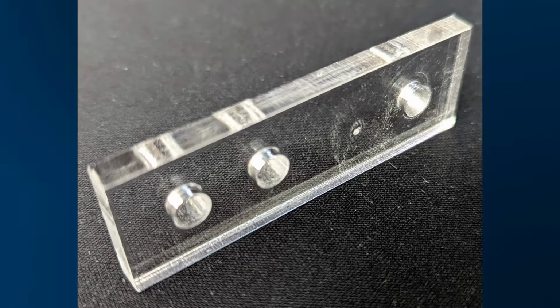Now, even if you had the ability to pull all of those nasty fumes out, run them through a scrubber, and safely exhaust them, it's still not something you want to stick in the laser cutter, primarily because of the objective lens that your laser is going through. This is the lens that's actually closest to the workpiece, and it typically has a lot of coatings on it to enhance its function. Those coatings really do not do well with almost anything. They typically are very, very delicate. Only clean them with certain kinds of non-abrasive cleaners. Be careful, don't talk bad about them when they're looking.